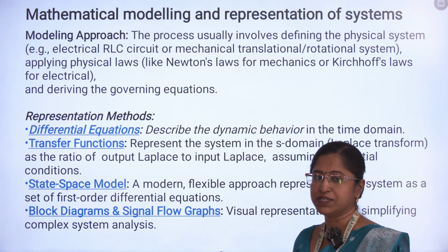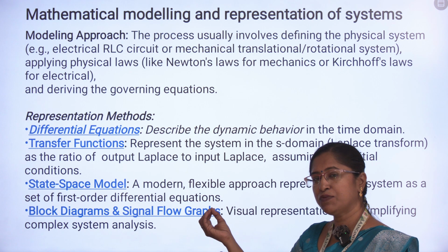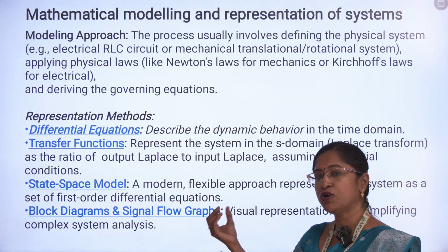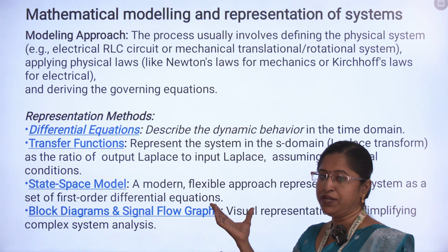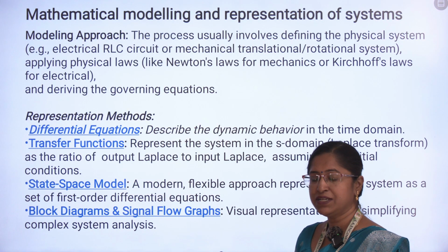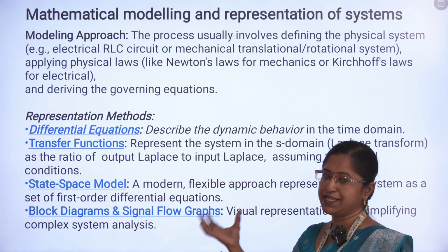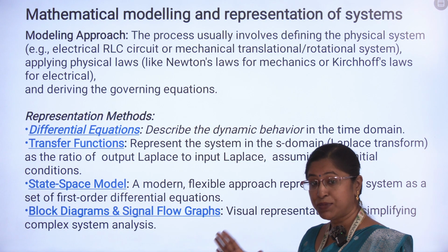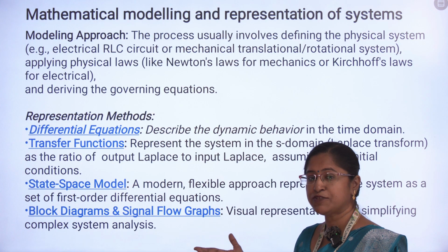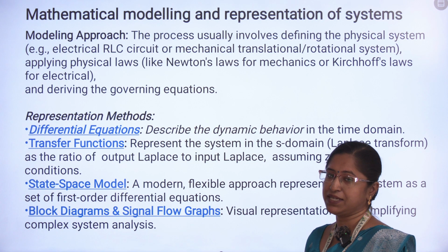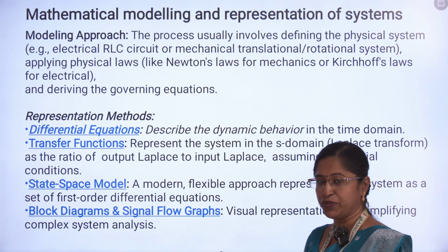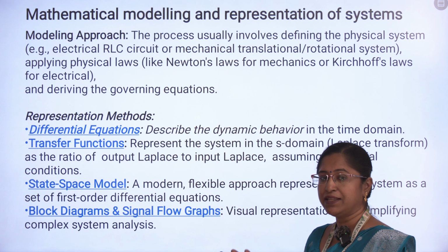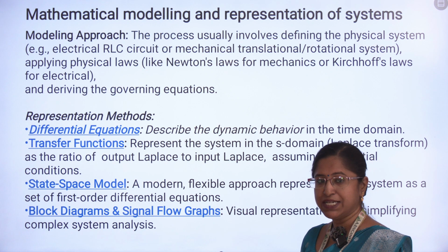Second one is your transfer function. The differential equation is mostly used to define the governing equation of the system in time domain. When we go for transfer function, it is used to define the system in S domain. The definition of transfer function is the ratio of the Laplace transform of the output to the Laplace transform of the input at zero initial conditions. So for any system in S domain, if you know the output and the input, you take the Laplace transform and the ratio of that will give you the transfer function of the system.